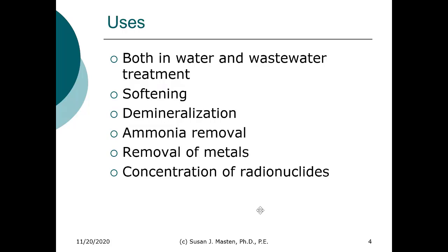So just in terms of thinking about where we can use ion exchange, it can be used in water treatment, wastewater treatment, and industrial treatment. We've talked about lime soda ash softening. We can use ion exchange to remove calcium and magnesium. Those of you that have a water softener at home, that is an ion exchange unit. We can also use it for demineralization. So we can remove more minerals than just calcium and magnesium.